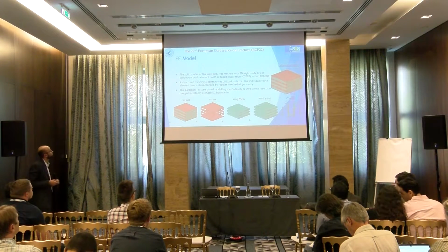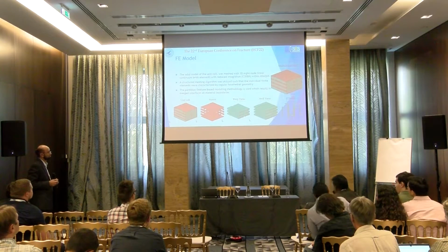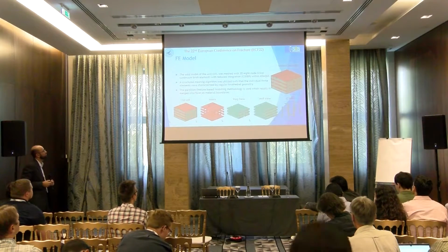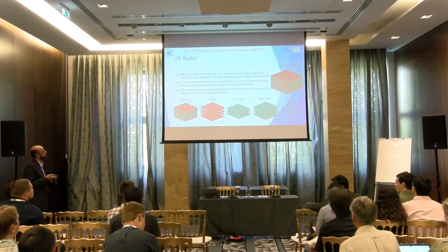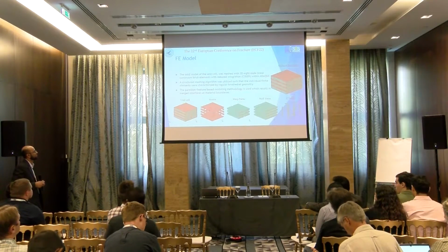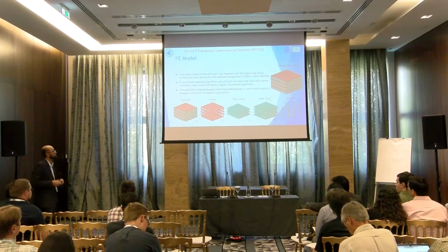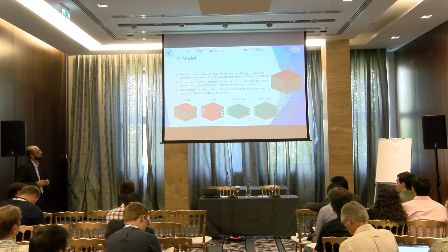Now coming to the FE model, basically the partition feature-based modeling methodology is used. We have partitioned each section, and their interfaces have common matrix, like matrix with warp yarns, weft yarn, and Z yarn. So there is no cohesive zone defined between that, and special care has been taken while